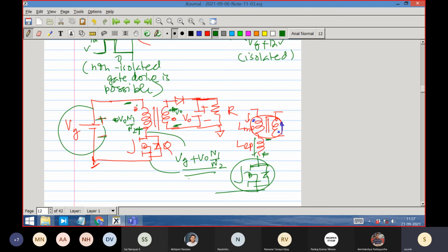So this voltage is therefore the device voltage VQ during the off time. This much voltage will be appearing across this, and along with that, if there is leakage inductance, some voltage will be spiked, and that voltage, if the leakage value is too much, the device may be killed or destroyed. So normally all the actual practical converters come with a clamp circuit.